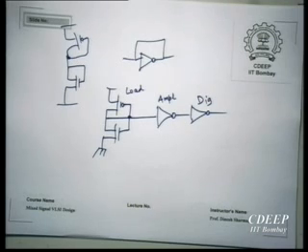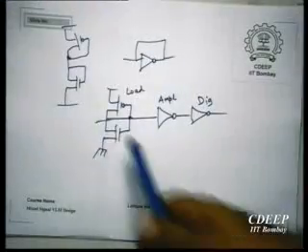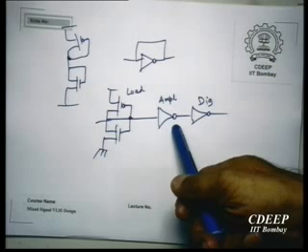Okay, so it appears in layout as if there are three inverters to the incoming line. The first one is a shorted inverter where the input and output are shorted, and you can see from the feedback that as the input rises the output falls, therefore it draws huge current from the output, therefore its input impedance is very low, which is what we want. Input is given here. Okay, so this ensures that this output doesn't swing ever by a large amount, and it also ensures that this voltage is matched to the trip point of this.